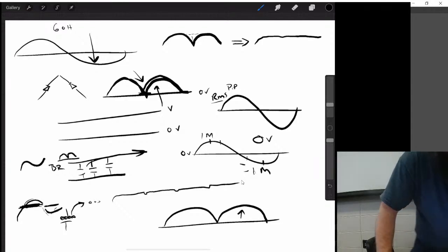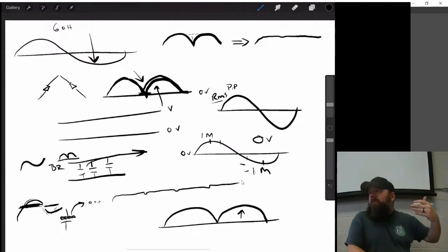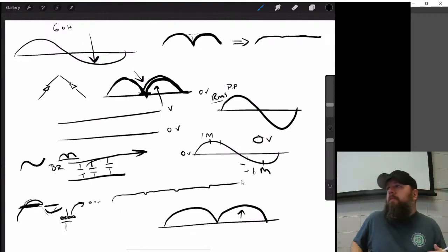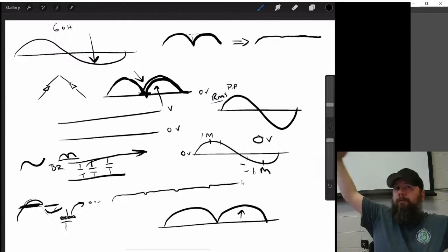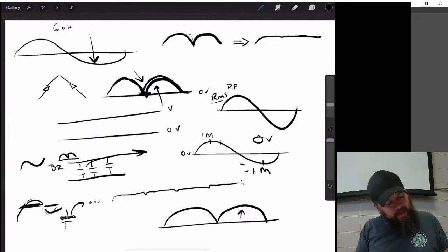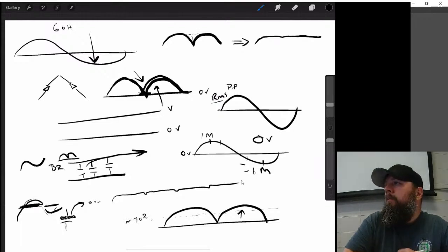All right. So through math, we flip that side up by squaring it. We average that, and then we take the square root of it because we made it artificially big to make it flip up, right? And that gives us some number, I think near about 70% of wherever that went up. So let's say around 70% of that. Okay. Cool. And when you read RMS on a meter, that's a better reading of the amount of energy that you've got to use. Okay.